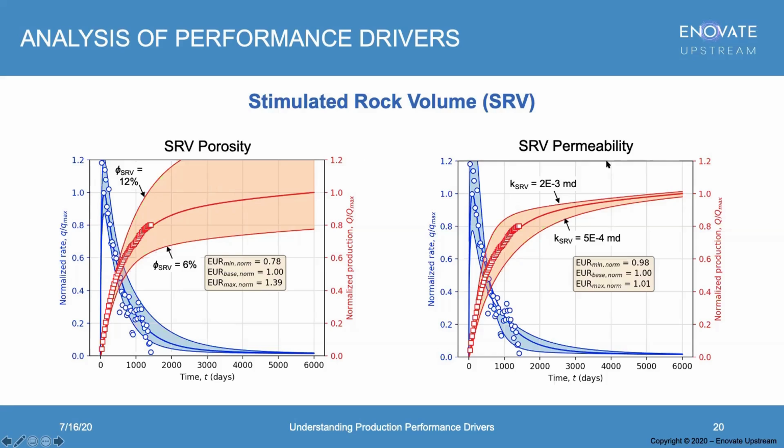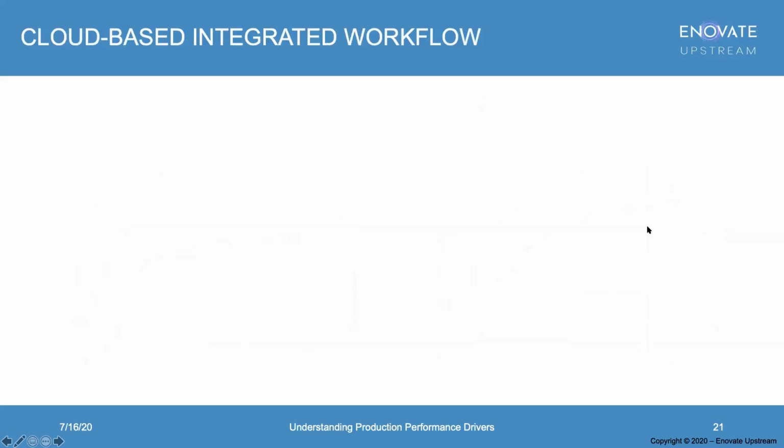So we have observed that using fracturing techniques that encourage fracture branching around the hydraulic fractures, and SRB permeability, on the other hand, does not affect EUR as we should expect. However, it plays a role in mid to late time production, and even early time production, because what you see here within the envelope is the production that you would have left behind if you had gotten a low SRB permeability.